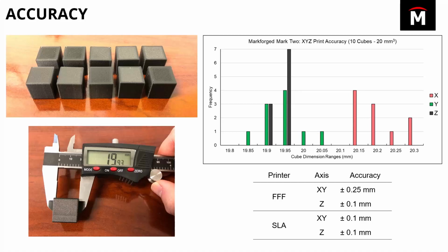That's straight from Formlabs data, where they found they get almost unified accuracy across all three axes. And again, SLS floats right somewhere in between. Also, with Formlabs testing, they tested with a variety of different materials, and they found that depending on the material they used, they saw different accuracy. So again, that feeds back to how accuracy and material are tied together.